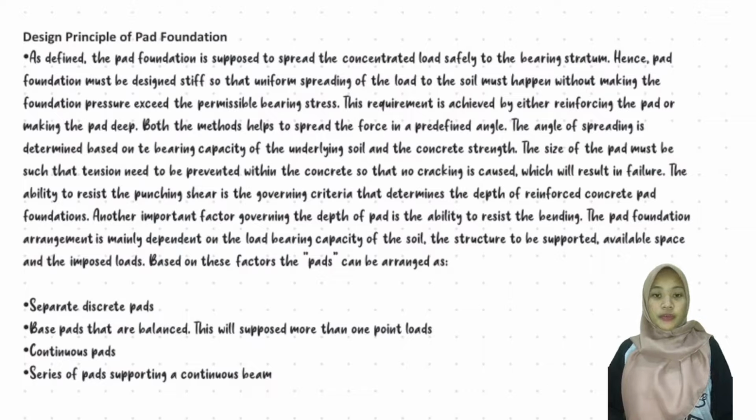Design principle of pad foundations as defined. The pad foundation is supposed to spread the concentrated load safely to the bearing stratum. Hence, pad foundations must be designed stiff so that uniform spreading of the load to the soil happens without making the foundation's pressure exceed the permissible bearing stress. The requirement is achieved by either reinforcing the pad or making the pad deep. This method helps to spread the force at a predetermined angle.